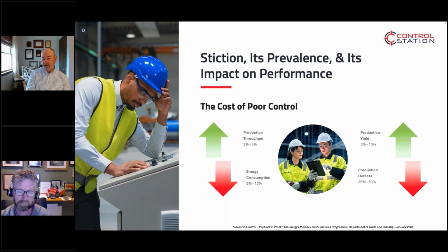And we all know that the degrees of efficiency you get by getting closer to set point matter significantly. So if you have a valve that has, let's say, 1% stiction, and maybe that valve is only 20% open, that means it's going from 19 to 21, which is quite a swing on a valve that's 20% open.